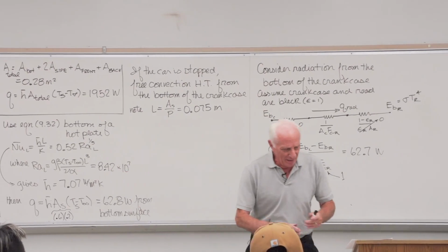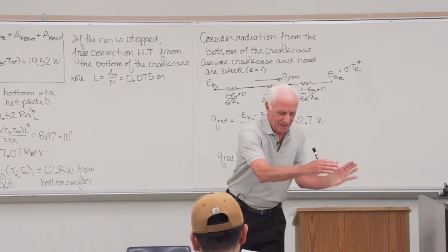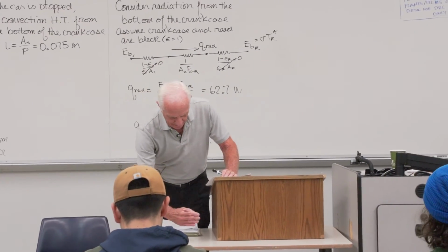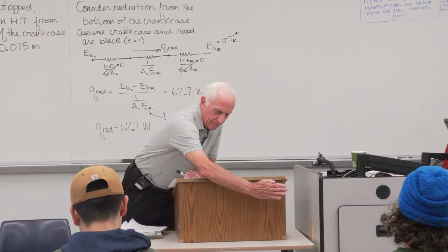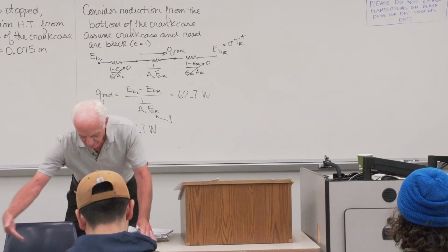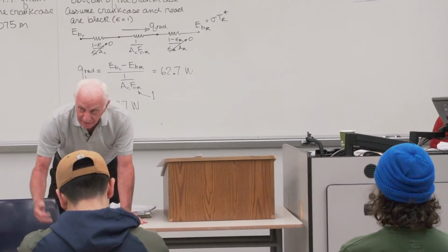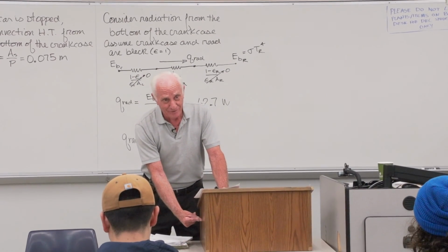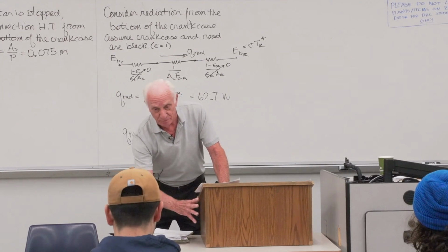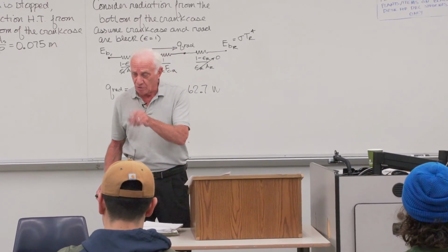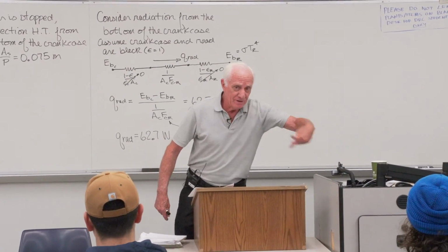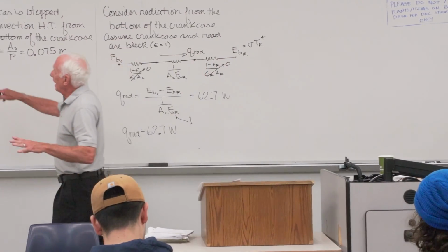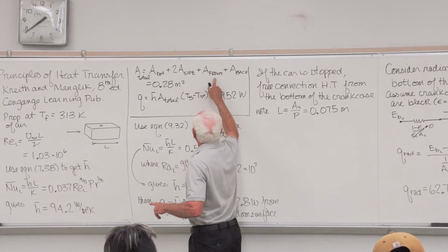That equation we did is for about, here's a crankcase. Here's the engine above it. Let's say the bottom's open. Air comes here, hits this edge, boundary layer builds up. Great. On the bottom, air hits here, boundary layer builds up on the bottom. Got it. The front, air hits here, boundary layer. Oh, no, it's messy. Really messy. The air spreads out in all directions. And even worse than that, the backside, a wake region, turbulent eddies, a boundary layer back there? Oh no, not even close. So, I believe that. I don't believe those two guys.